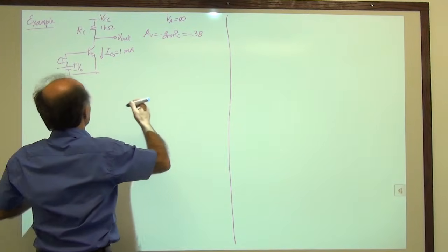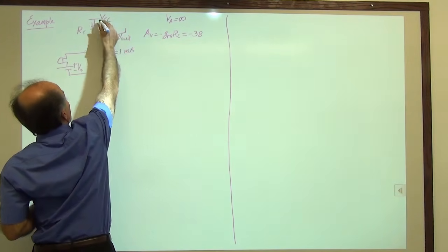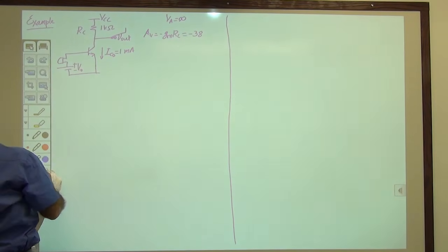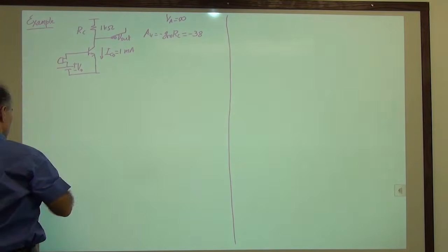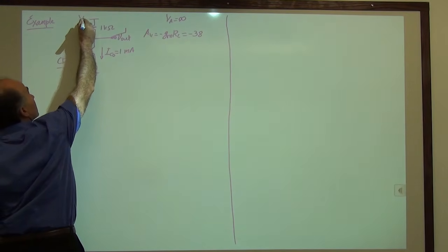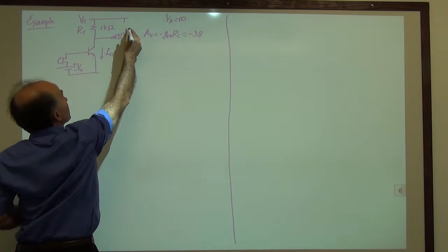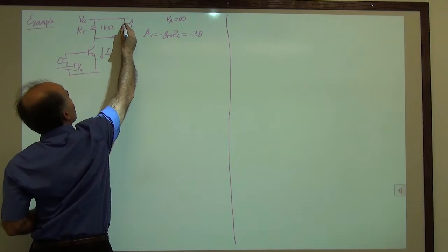So we will attach the speaker right here. That's our output, right? Let's attach it just to VCC. So let me do this a little better. So we'll put VCC on this side, and we connect our speaker between these two. The speaker sometimes is shown by this symbol.